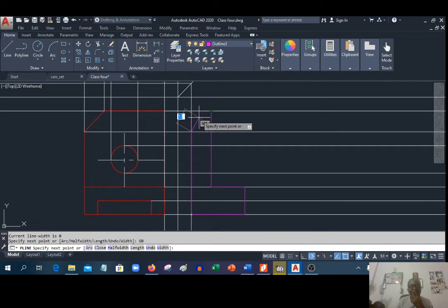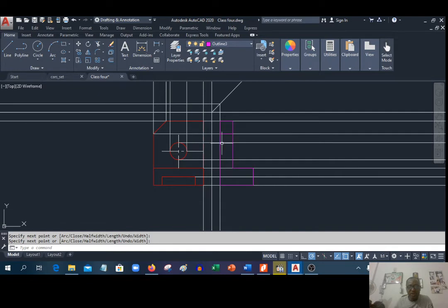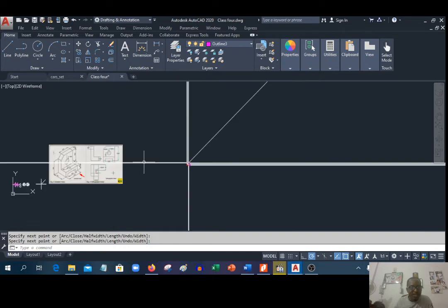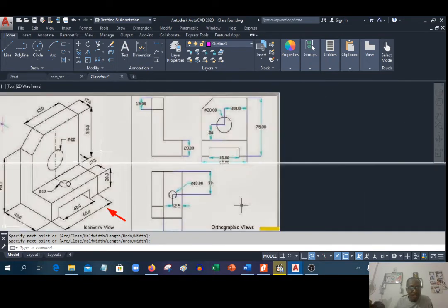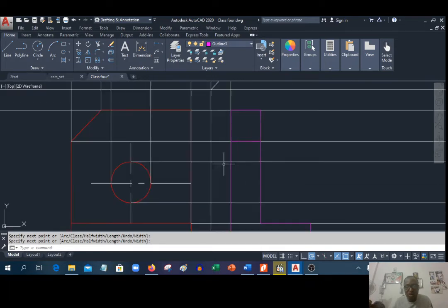All we need to do is just let it cross and end. Repeat the line. We'll come here. It's a box like that we're going to see, right? We'll not see the bevel shape, right? So it's a box like we'll see there. The next thing we're going to see is this circle. If the hole passes through, we're going to see it as a hidden line, right?